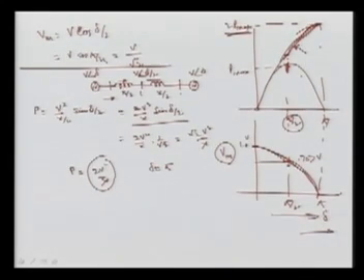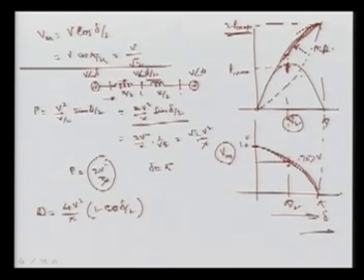So it is increased. Now you can see the reactive power, this Q, what will it be under this condition? It will be nothing but 4 V square upon x, you can derive it, times 1 minus cos delta by 2. And now you can draw the equation here, and this Q will appear like this.